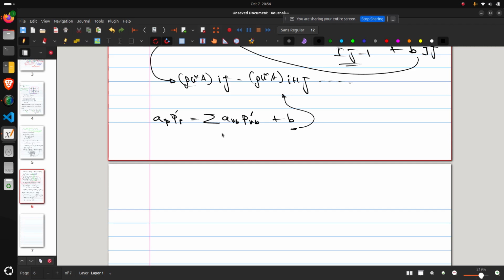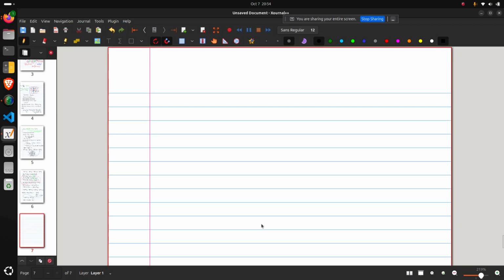So now that we have this equation for the pressure correction term, what can we do? We can solve it using any kind of method that we want, explicit direct method or iterative method, whatever is feasible to us. Once that is done, we have obtained the pressure correction, and then we can apply it to get the velocity correction, and finally we can correct the velocity. Okay, so let me give you a brief flow chart of how this SIMPLE algorithm operates.